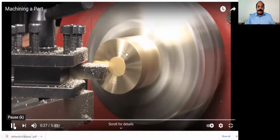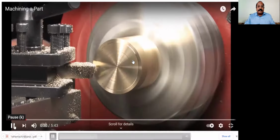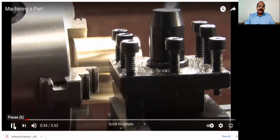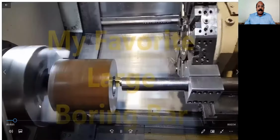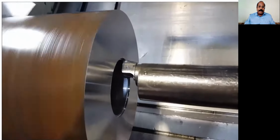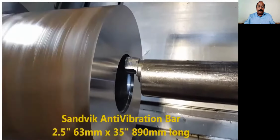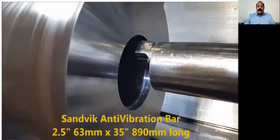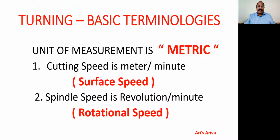This is the facing operation, and facing is another operation in turning. The third one is the boring operation. There are three: turning, facing, and boring. So this is a boring operation. Boring makes a hole in a more accurate way. So these are the three essential operations in turning, right?